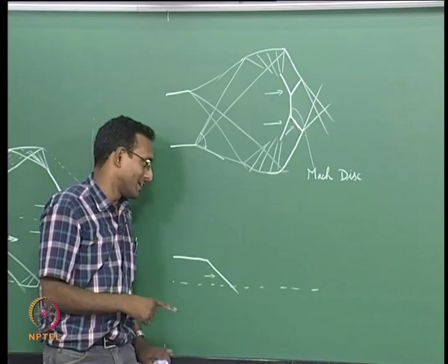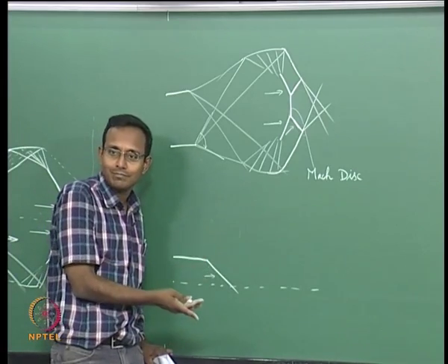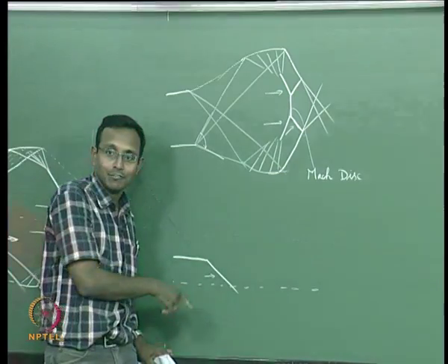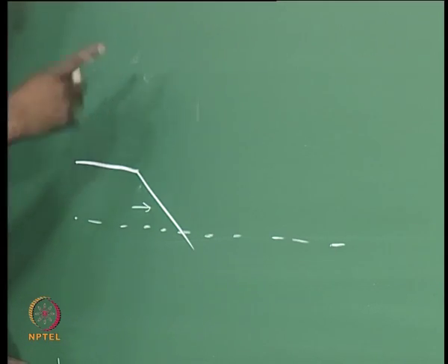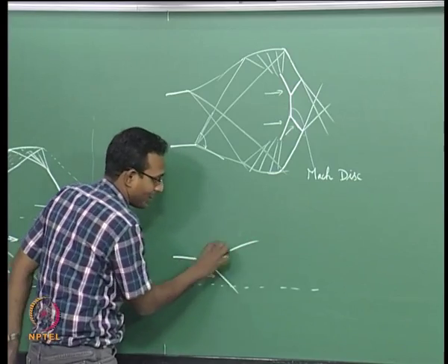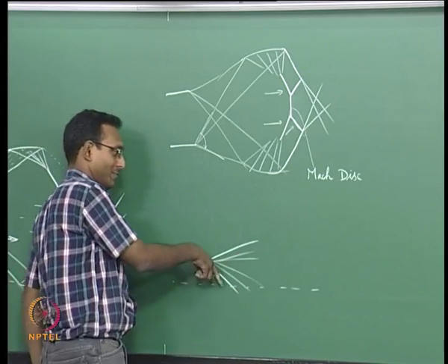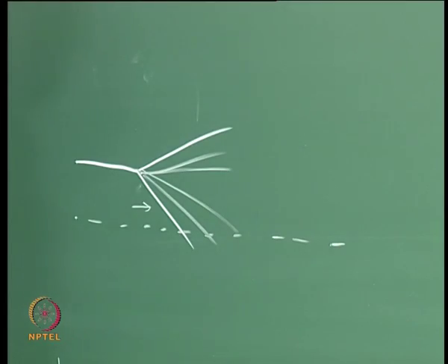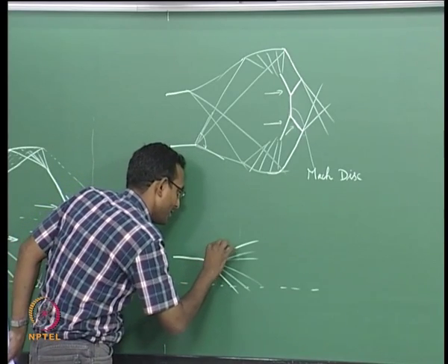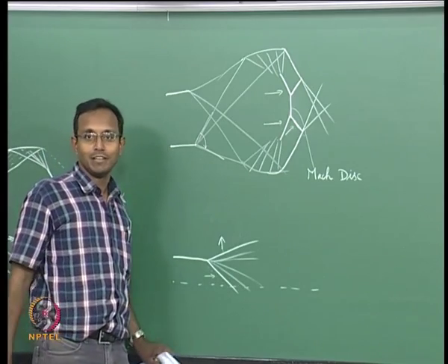Okay. If I think about that case, I can tell that my angle can be more than 90 degrees also, right. Even if my Mach number is 2, I can have more than 90 degrees angle change if my pressure is extremely low here. So let us pick such a case where my expansion is this wide, this full region is my expansion wave, this is all my expansion fan, everything inside is expansion fan. If that is the case and my flow is turning like this, it is going to turn finally out at some angle like this, that is also a possibility.